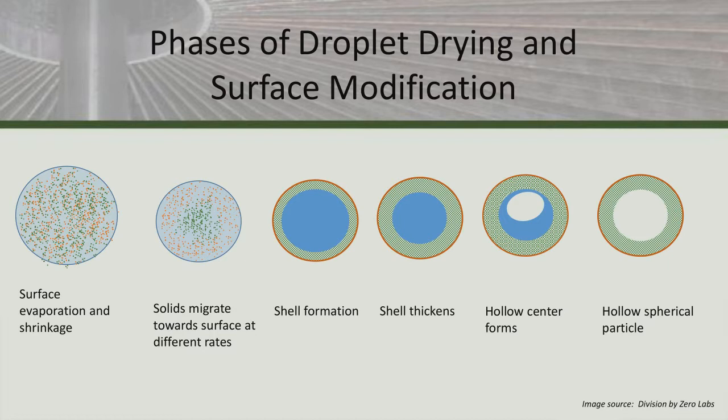But actually how that happens is you can mix materials together before spray drying, and because of some pretty interesting mass transfer characteristics that occur when you're evaporating a droplet over the course of 300 milliseconds, solids within that will migrate to the surface, and they form this hollow shell, but they will migrate to the surface at a different rate.